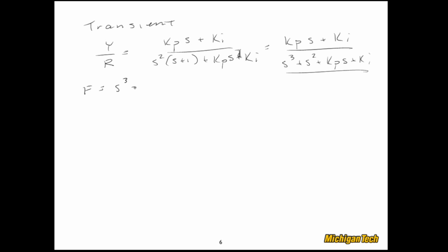Let's pull that out. And to investigate the transient response, what we'll do is just look for stability. Well, let's analyze the stability of this thing, because if we can find values of Kp, Ki where it starts going unstable, then that tells us that we're heading towards a region where the response is very erratic, likely rather fast.